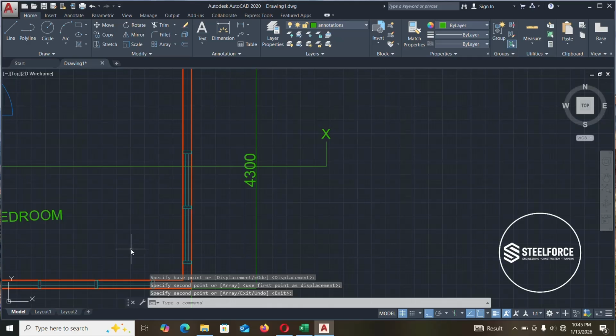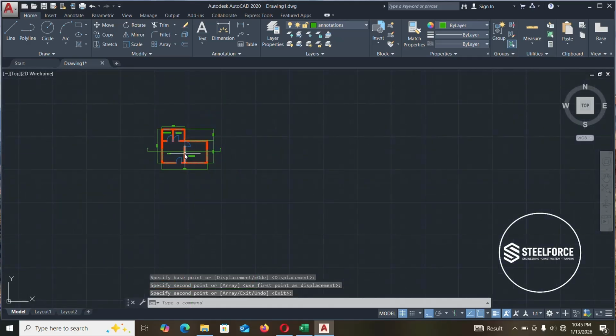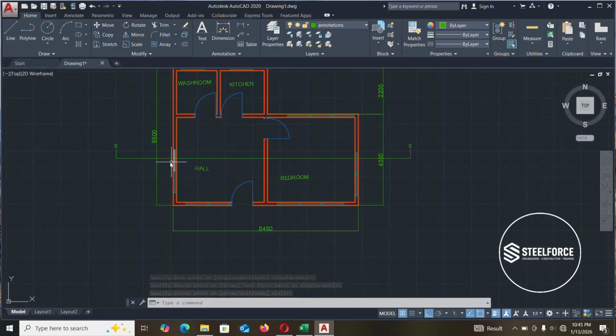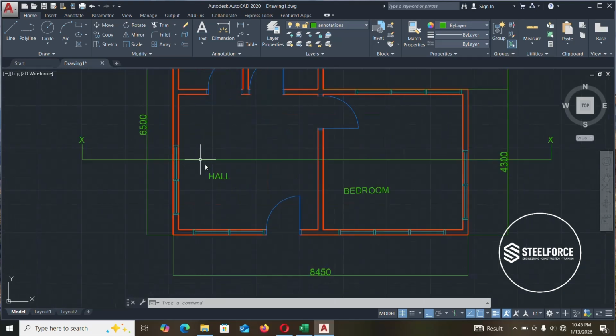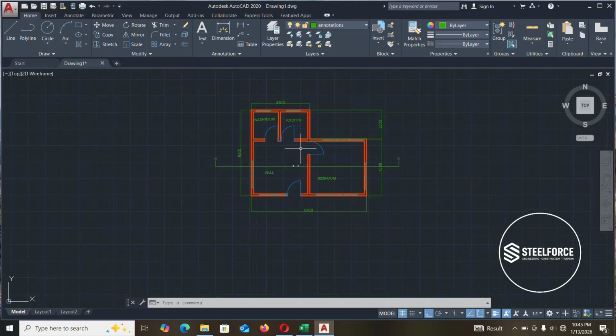So just the way we did our front elevation, we are going to apply the same method. But in the section, we take it from beneath the ground level. We assume all this part has been cut out and we are looking at the building from this direction.